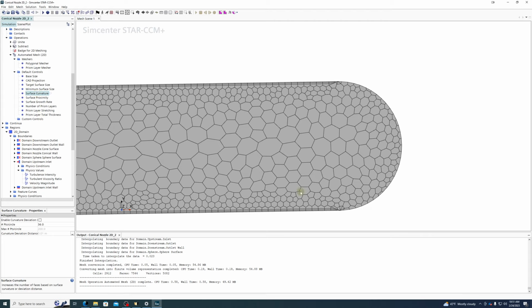Well, to demonstrate visually and to explain it a little bit, computers don't do circles. They do straight lines. They approximate circles with a whole bunch of straight lines. This is saying the minimum number of straight lines that you're telling it to use to make up a 360-degree circle. So right now, it is going to make sure there are at least 36 straight lines per 360-degree circle. That is, one line can span no more than 10 degrees of angular displacement. It can have more, and if you run into the minimum size requirement, it can also have less. But it will try and make sure there are at least 36 lines available.